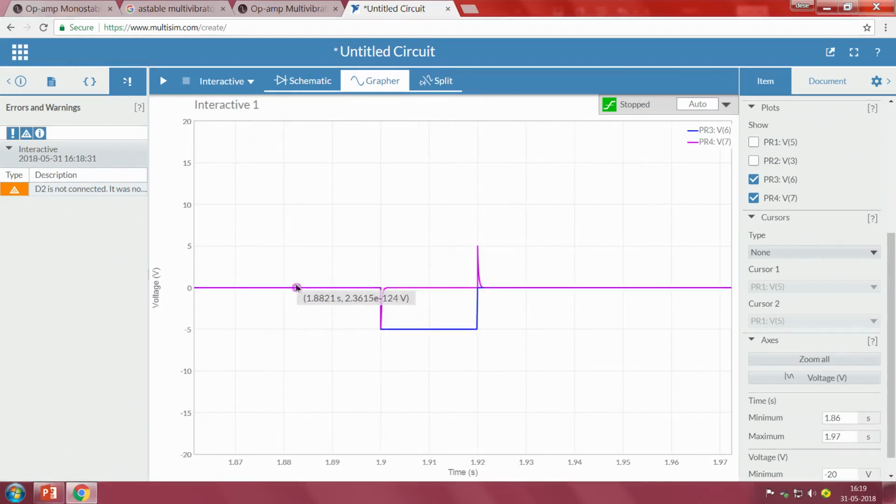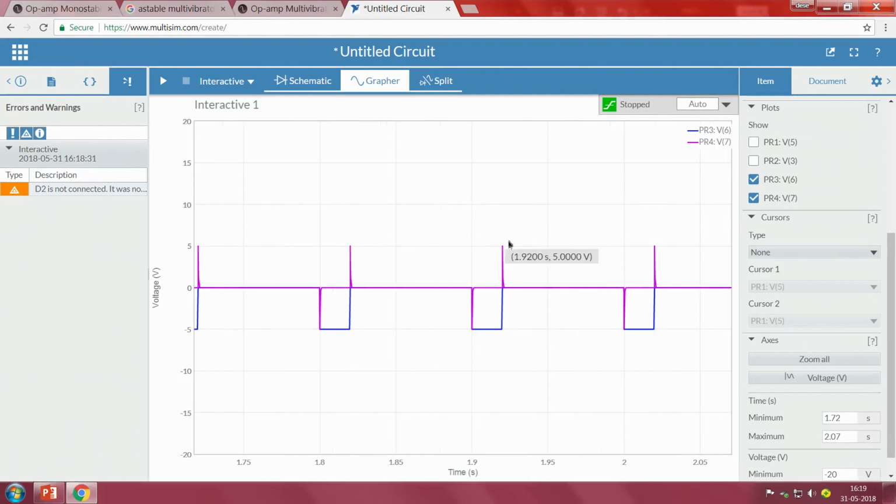Whenever we have a negative pulse, we get a spike, and again when there is a change from negative to ground, we get another spike. But if I get this spike, it will be problematic, as it allows the op amp to go to the plus VCC state, which should not happen.